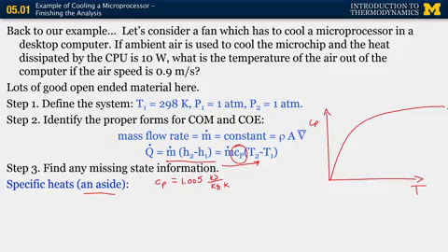So there you say, hey, wait a minute, you just told me we're assuming a constant specific heat, but look, this curve is a very strong function of temperature. How can we make that approximation? There are 2 ways you can make that approximation, and it's a good approximation. One is you say, my problem considers a temperature region where the specific heat really is approximately constant. You can say, I'm at a sufficiently high temperature where this is a good approximation. Alternatively, you can be in these regions here where you do see some variability to the specific heat, and you have 2 choices.